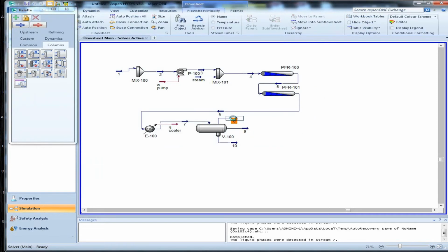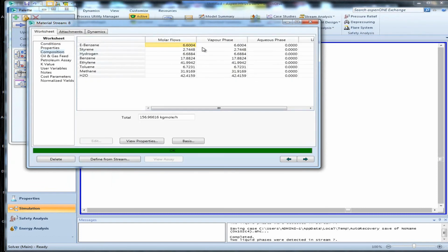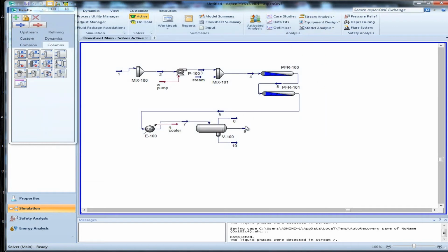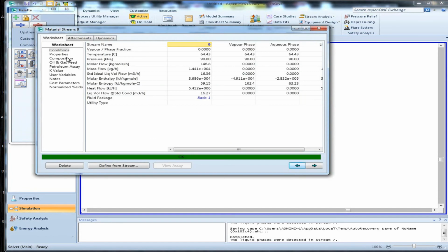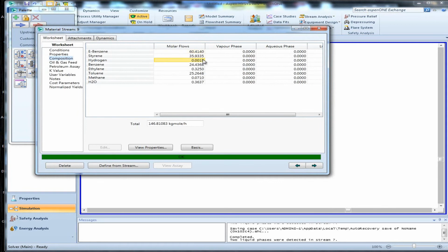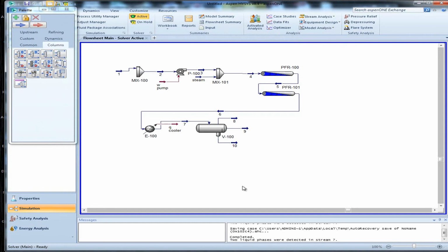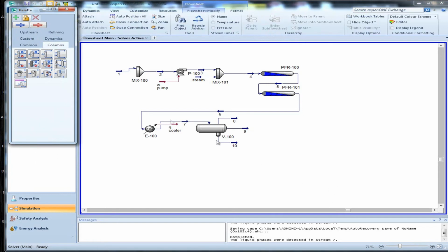Okay, now let's see on the top one. We do expect to eliminate all hydrogen here, and some light gas, methane and ethylene, which is good. Make sure that you don't have a hydrogen amount much to the separator. Okay, now it's time to put the distillation here.